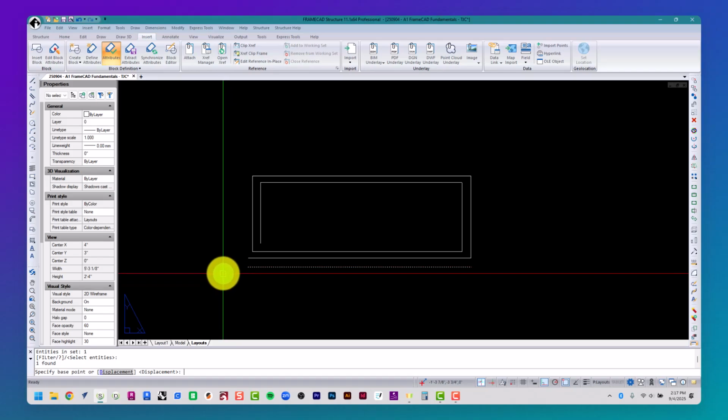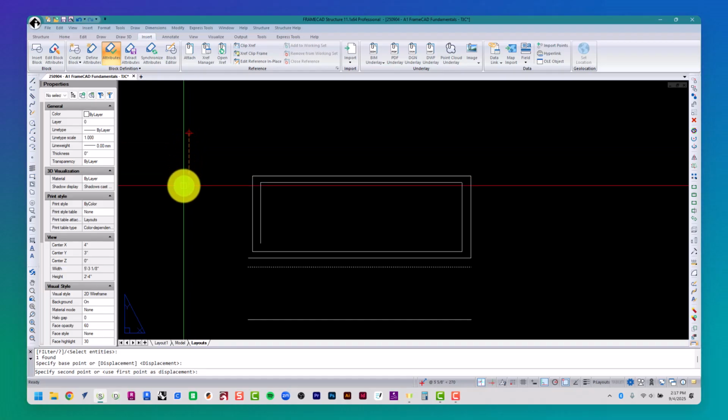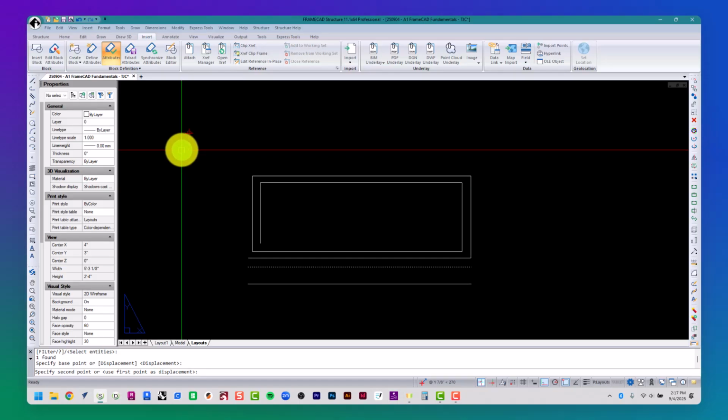So I'm moving a line, and I'm going to do it from this point, and wherever I move that point, this line will move in response to it, right? So imagine that this point and this line, this entity that I want to move, their relationship is locked. So if I move point A to point B, this entity below will also move and continue that relationship that it had with point A. And then just click, and now there's no commands.